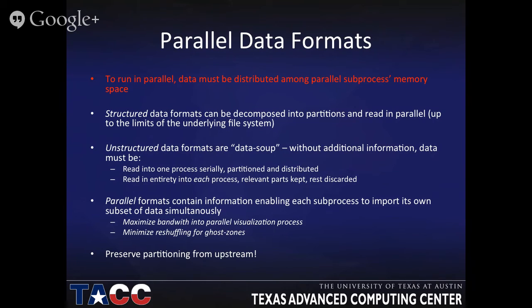And we can each read it in parallel, assuming that the hardware supports parallel I/O, right? So that's what we call a structured data format. And there are a lot of readers in both ParaView and VisIt that read in structured data formats and support this sort of automatic partitioning of the data into however many pieces it needs to be. And it's a wonderful thing. Again, unstructured data doesn't work real well.